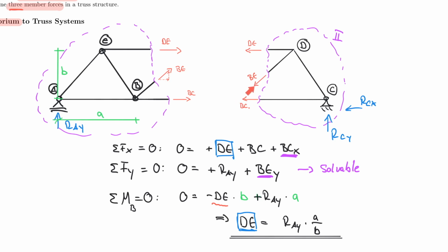So you should not get confused by the fact that the point about which you rotate the system is actually outside of your cut cloud, as I call it. So I call this here my cut cloud number 2, and the rotational point is outside of it. But for clarity, I'm going to draw the structure just with dashed lines here. That's often how you see it in books. So I will use my ruler here, and I will designate this here as point B. This is the point B, or node B, which is outside of my cut.